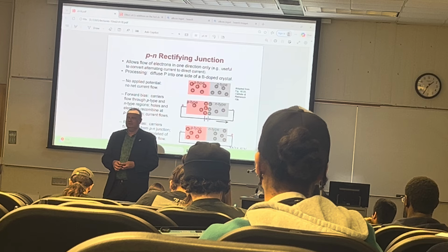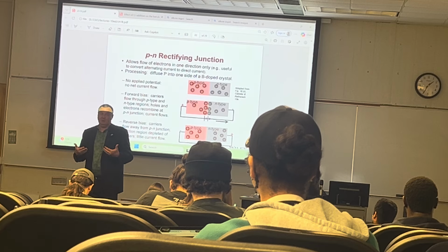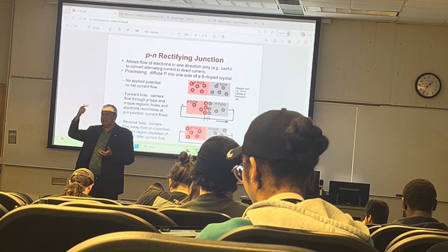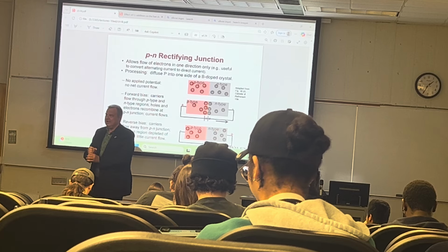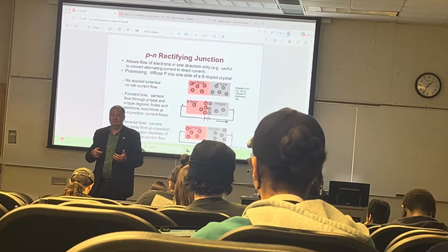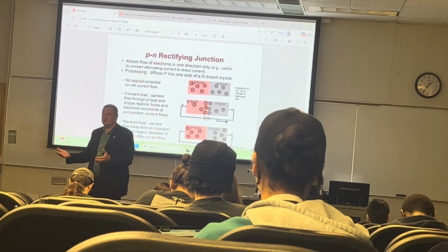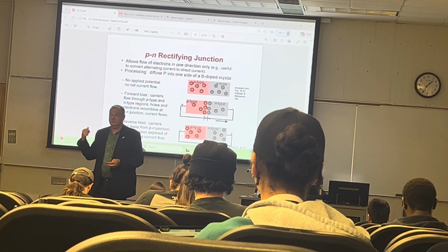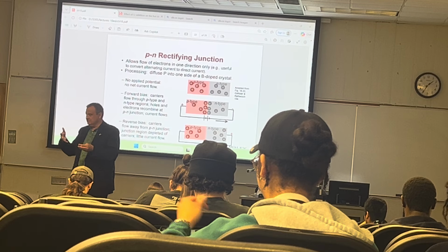How about mechanical? Okay. It's kind of like a civil and mechanical combined, because if there's an air conditioning system and a multi-story building, by the new code each AC has to have its own drain line, right, because it condensates. But in older applications, they didn't have a separate drain line, and it's an older building which you cannot retrofit with an extra line, like in New York or in Florida somewhere that was built in the 60s, and they're all draining into the same pipe.